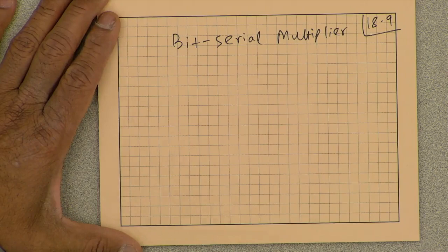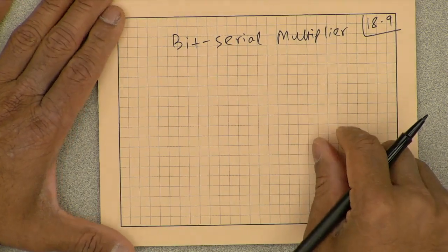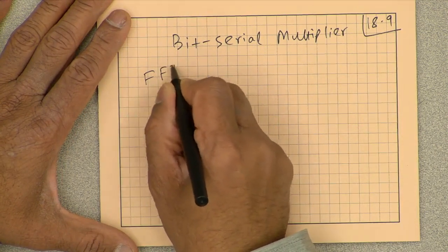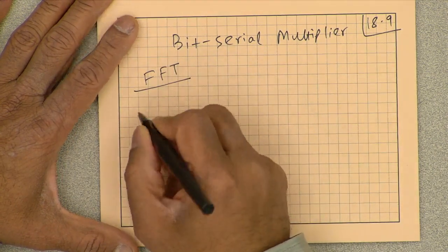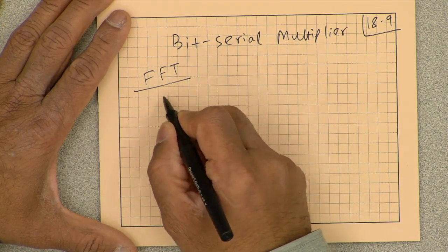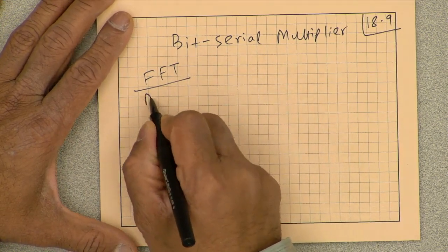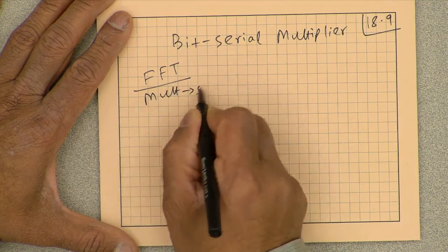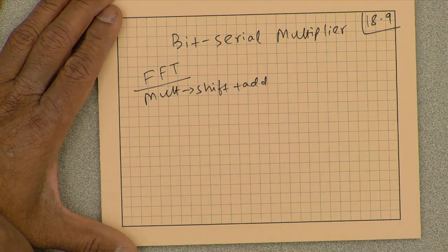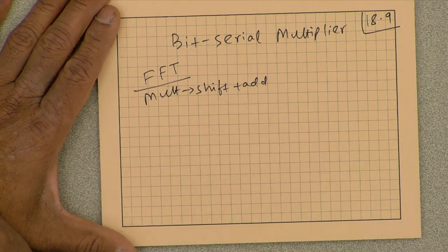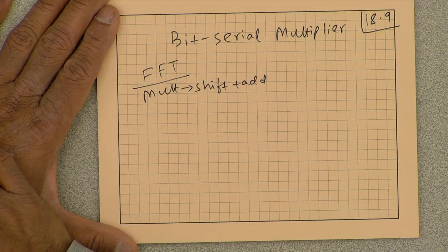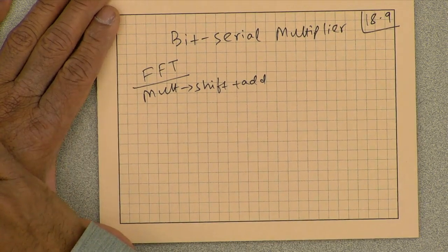So in those days, algorithms like the fast Fourier transform came along because the CPUs, the IBM computers, had shift and add. So multiplication was computed by shift and add. As long as we can reduce the number of multiplications, then we can reduce the number of cycles, and that led to a number of fast algorithms, one being the fast Fourier transform.